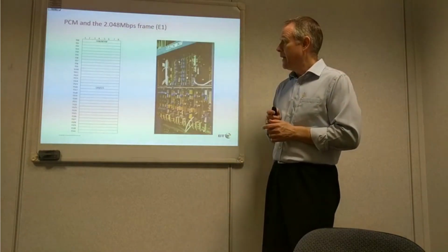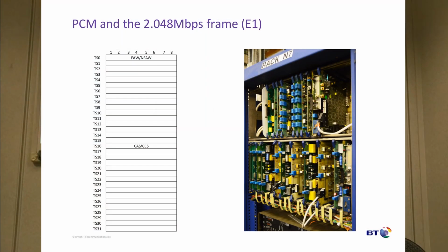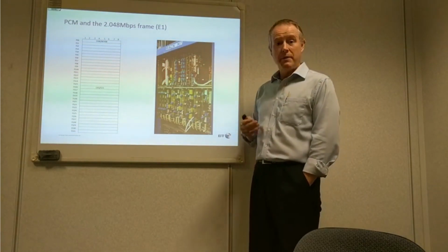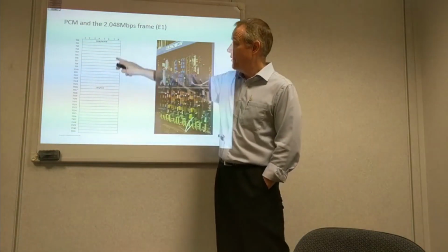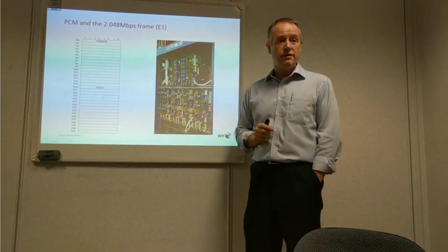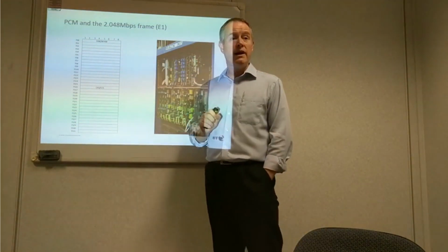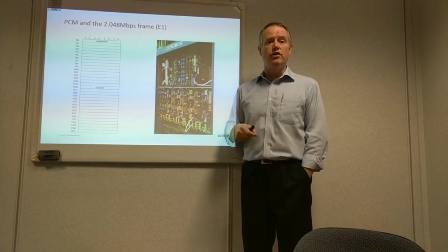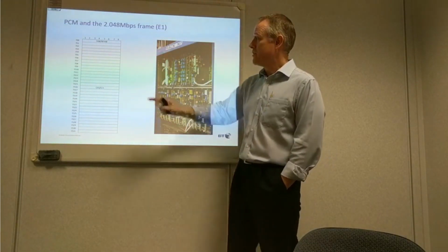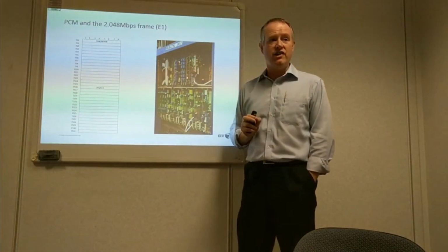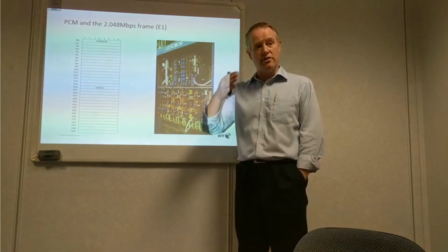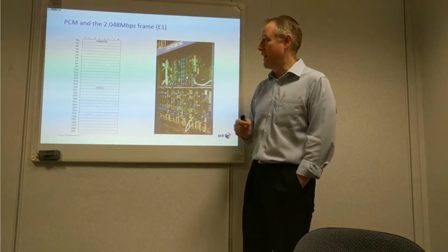And then we actually developed that frame further to deliver a whole range of access circuits as well, where if we take an example here, we've got the frame from an E1 circuit, so 32 time slots, 64 kilobits per second per time slot. Time slot 0 is what we call a frame alignment word, or not frame alignment word. So this actually does frame synchronization, alternating between frame alignment and not frame alignment, so you actually get the correct